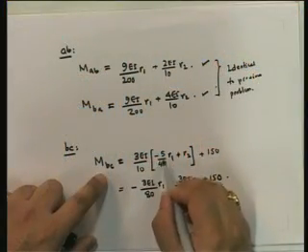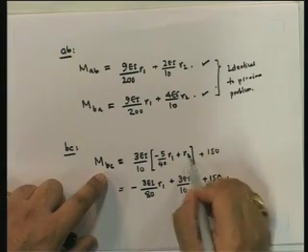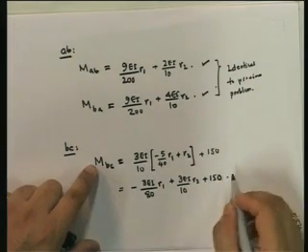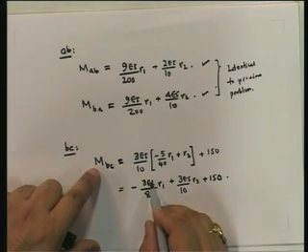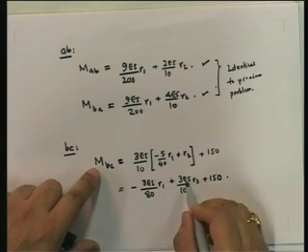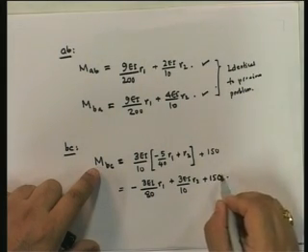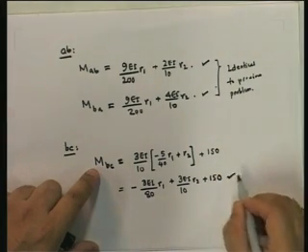Now BC, because C is a hinge, we had to write a modified member force deformation relationship, which only relates the moment at BC with the theta at BC, because we incorporate the fact that MCB is equal to 0. So I have substituted theta BC. If you look at the kinematics, theta BC is minus 5 by 40 R1 plus 1 R2. If I substitute that into this and rewrite it, I get MBC is equal to minus 3 EI by 80 R1 plus 3 EI by 10 R2 plus 150. So these are our relationships.